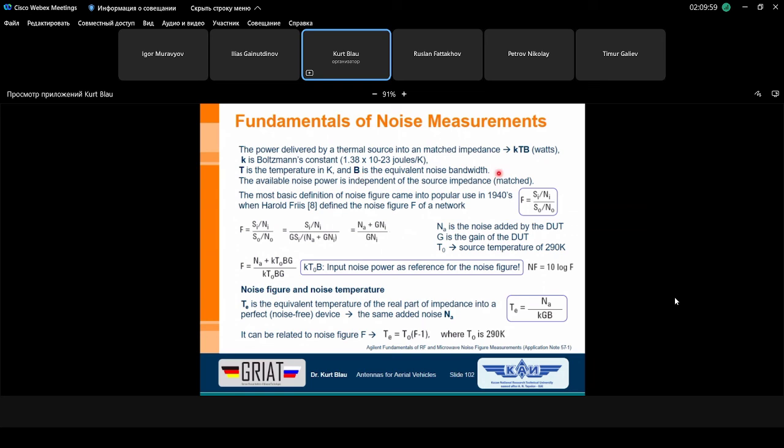It's not only the bandwidth that we measure. For instance, if you look at a small band receiver or a selective receiver, which has a certain bandwidth and a certain steepness of the edges, to receive or amplify wished signals and keep out other unwished signals, distortions, and so on, this bandwidth of such an amplifier is not the same as what is meant here.